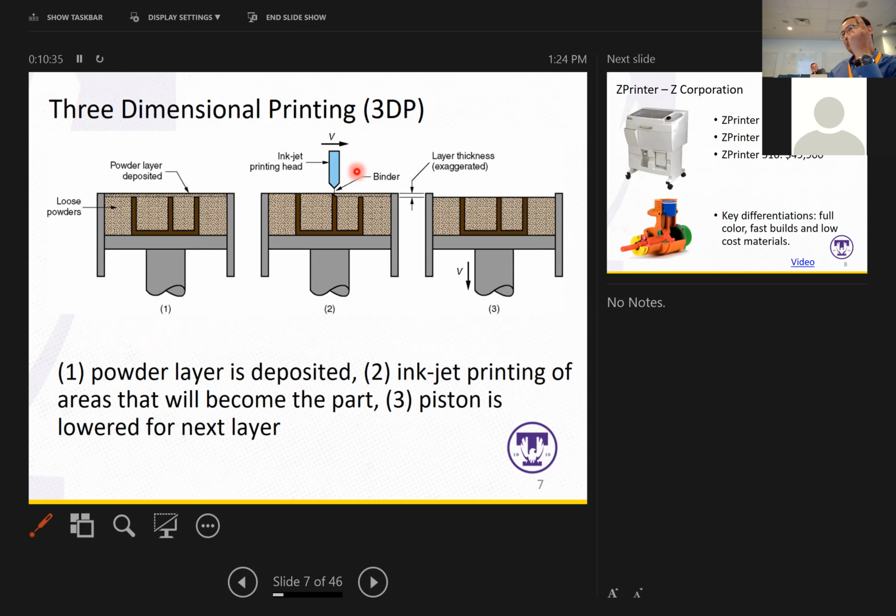But based on this concept, as I mentioned in the very first few classes, there are some low-cost metal printing processes. They use a very similar concept. Basically, they make their green part following these steps. But additionally, they have a sintering process to melt the particles a little bit, to sinter the particles a little bit, to form a solidified part.